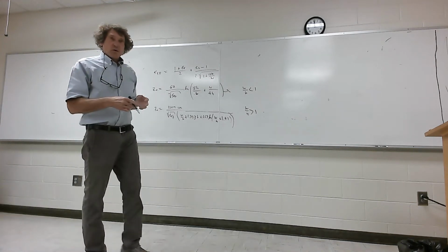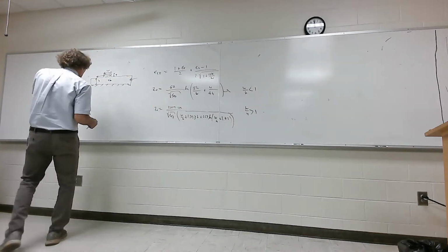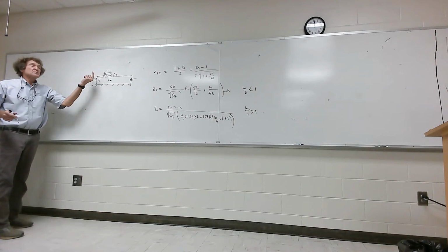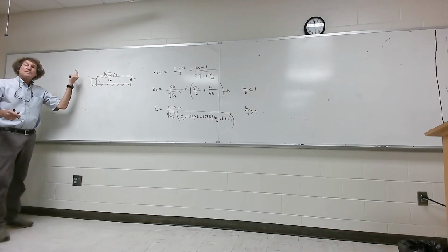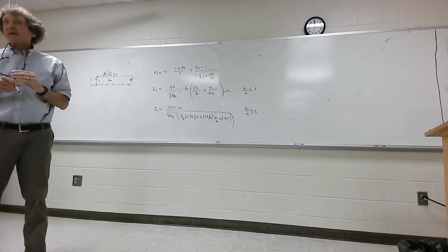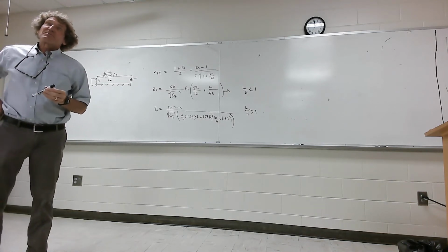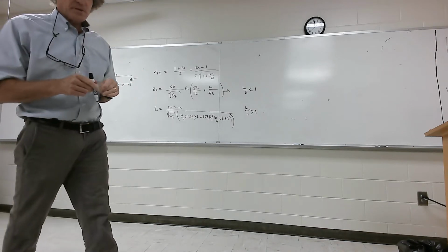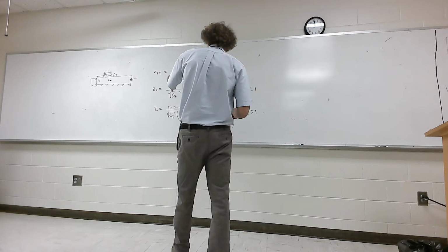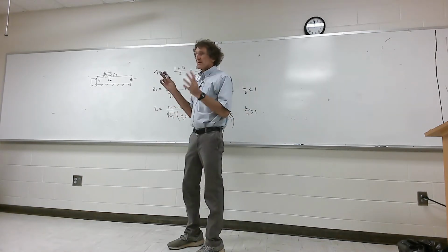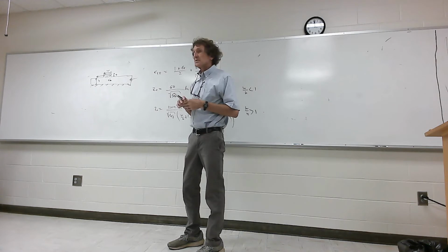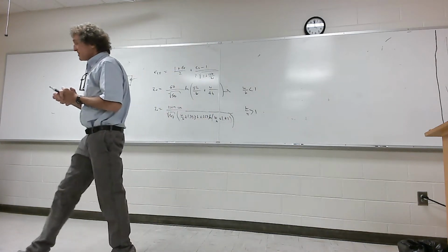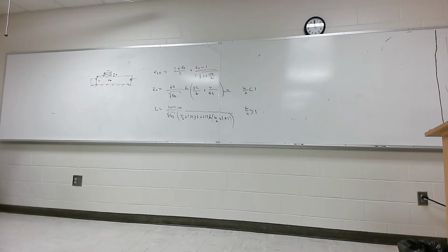So what we did, we went through and did modeling for all sorts of thicknesses, all sorts of epsilon relatives, and all sorts of widths. And we came up with a family of curves that approximated the actual characteristic impedance and the effective permittivity, and really the real thing is the characteristic impedance. So there were design formulas when we published this. But I realized one thing about this. In industry, they could care less if it came from Maxwell's equations or somebody just winged it and got it right. They wanted accurate design formulas. That's the only thing they want. So in industry, you can more or less not worry that much about how it was developed, but it has to prove its worth in the processing.